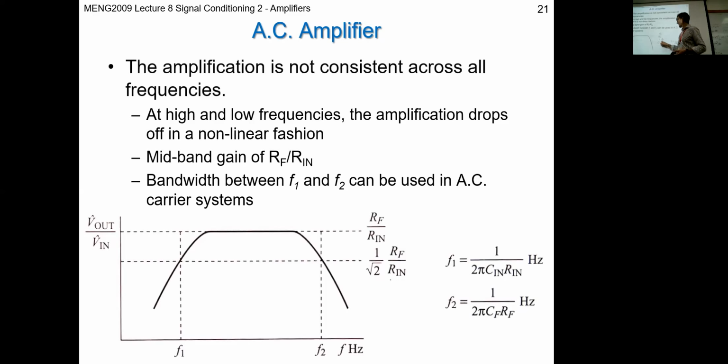You notice that here we have another dashed line, just slightly below the unity relationship or the standard relationship. This actually represents your bandwidth, right? And you've heard bandwidth is a familiar term. This is what it means. It means the frequencies between which you get less than 3 decibels drop off in your amplification.